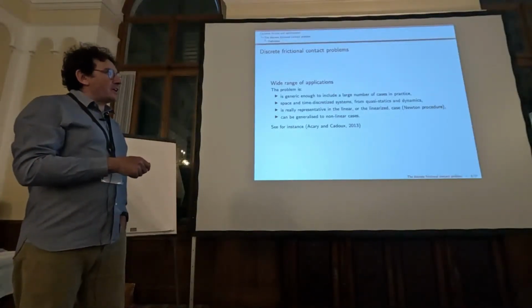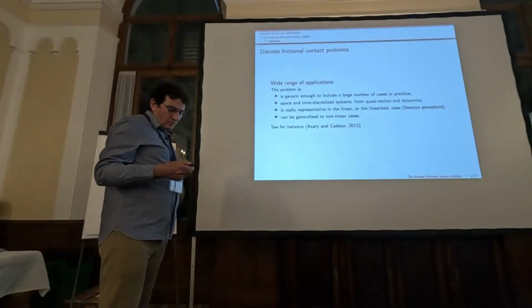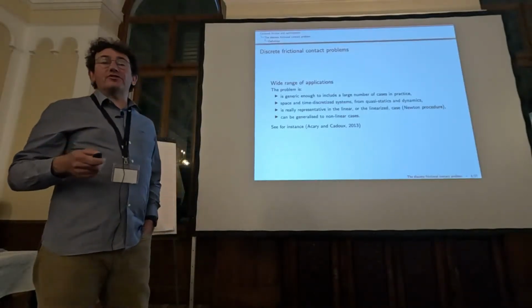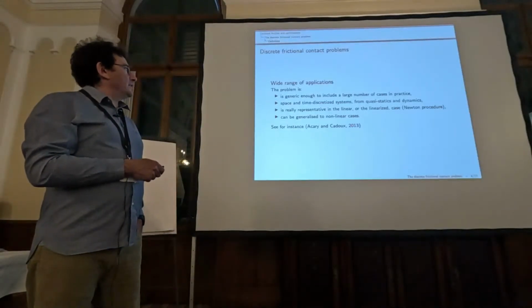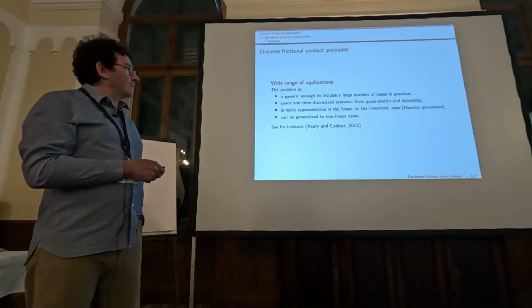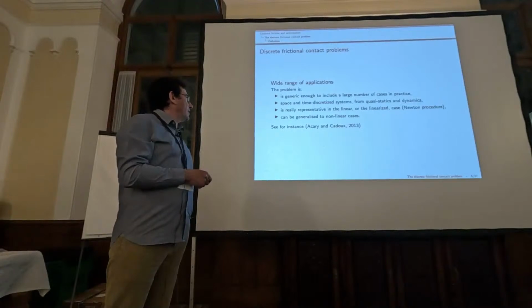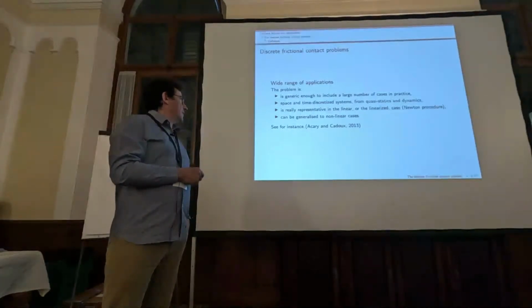At least in the linear case, it is quite representative of the problems that we have to solve if we want to solve contact and friction problem at each time step or each load increment. It is linear in some sense, but it can be used inside the Newton procedures if you linearize the systems.